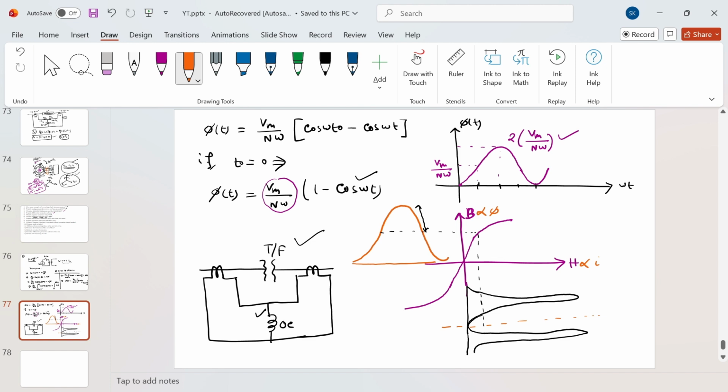The waveform is even in nature. So you will get the cosine terms and also the DC component, because it has only positive quantities. But you cannot comment on odd or even harmonics, because this figure does not have odd half wave symmetry.